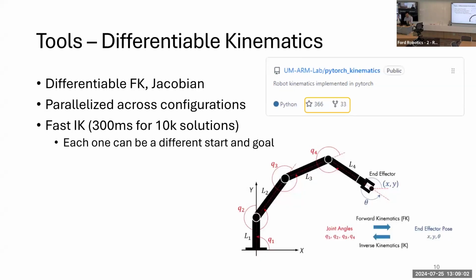I've also implemented a differentiable kinematics library that is useful inside dynamics functions where we want to solve inverse kinematics problems to multiple goals in parallel. We can solve 10,000 solutions in 300 milliseconds.